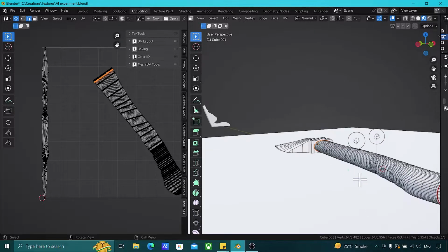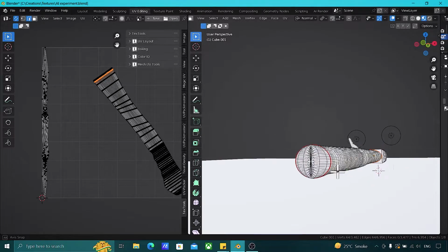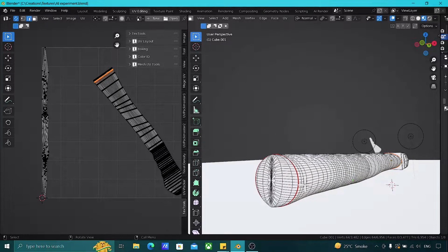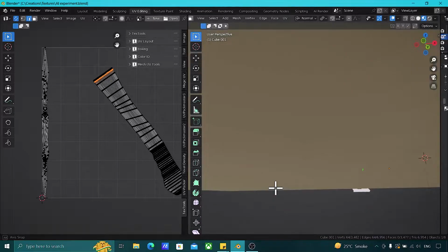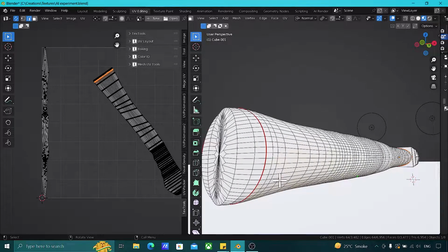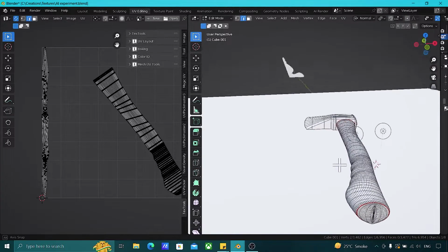All right, but it won't be completed before the third rule. That is, we need to connect these two seams in order to make Blender understand that we want to unwrap the texture from an exact point. So by that, we need to place it somewhere below visibility. Like if the X is visible from this angle, the seam won't be in the front.